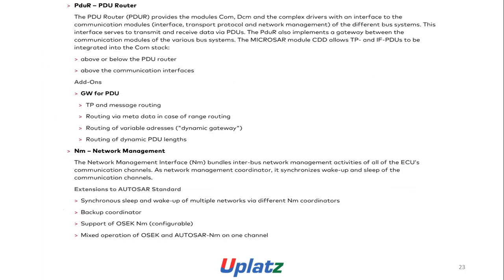PDU router, PDUR, provides the modules COM, DCM, and complex drivers with an interface to the communication modules: interface, transport protocol, and network management of the different bus systems. This interface serves to transmit and receive data via PDUs. PDUR also implements gateways between the communication modules of the various bus systems.